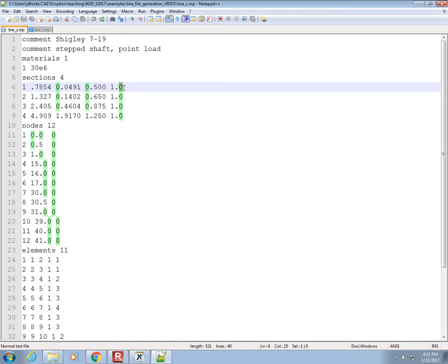You really only need to worry about the value of this if you care about the transverse shear calculation. But the correct value for a round beam is actually 4/3, or about 1.333. And that's actually true of the half height here as well. If you're not using the output of stress, then it doesn't really matter what values are in here, because those do not influence the deflection calculations. The only material property that influences deflection is the moment of inertia right here.